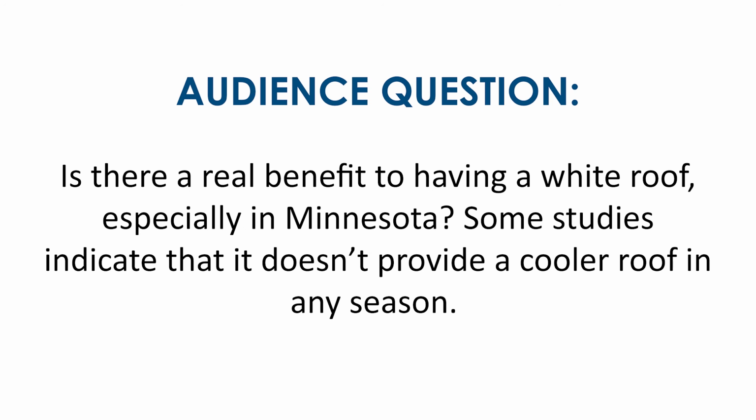We typically see no benefit to a minor penalty for white roofs in Minnesota. No benefit at the building energy consumption level, let me phrase it that way. We have enough roof insulation for a new building, and buildings are heating load dominated up here. It's somewhere between here and Des Moines where we start to see a marginal benefit for having a white roof from an energy standpoint. Frankly, we have the white roof requirement here because if we don't, we get asked about it over and over and over. So it has a very low impact on the energy consumption of a building. But if we don't have it there, we kept getting asked about it, so we included it.